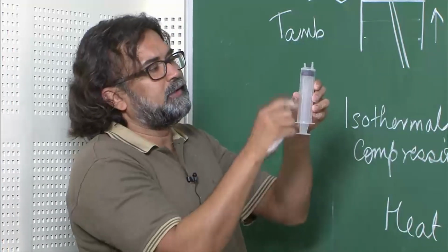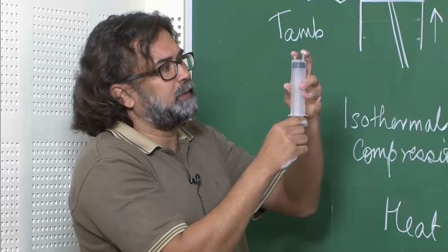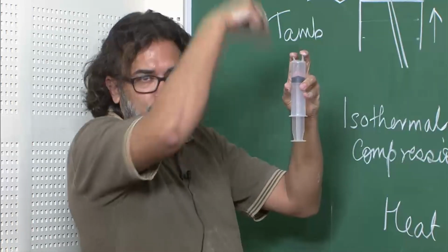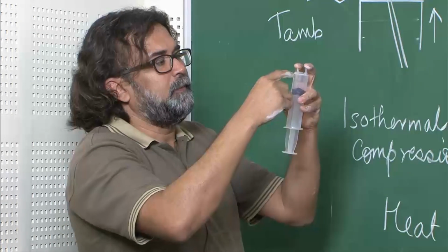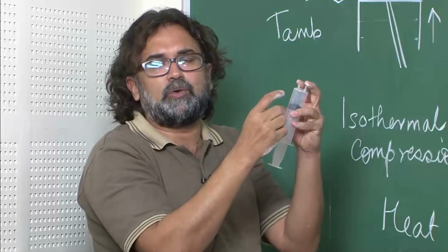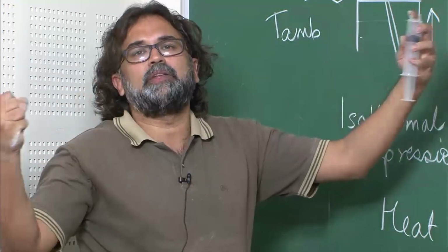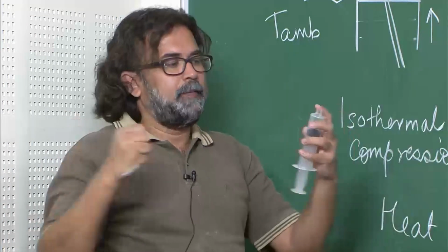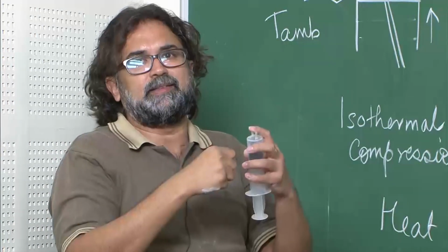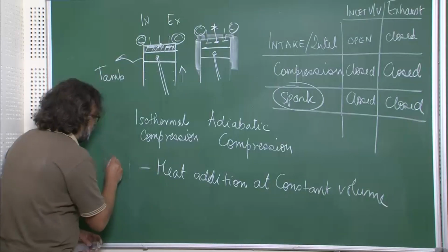So then what will happen is, as the heat comes in, the enthalpy of the combustion comes in, the piston already starts going down, because of the push which is created by the gas, and the pressure inside is more or less constant. You can idealize it as a constant pressure process. That means as the gas is expanding because of the heat which has come in, it is pushing the piston, and in that process it is trying to maintain the pressure inside to be constant.